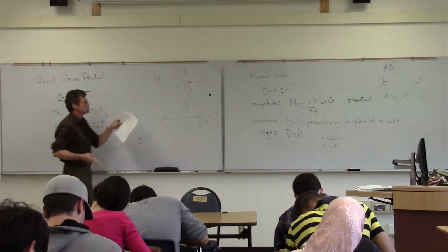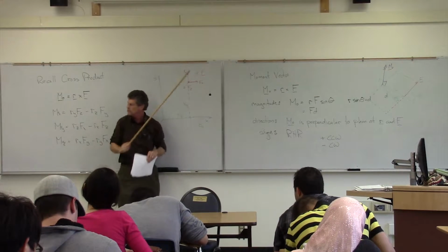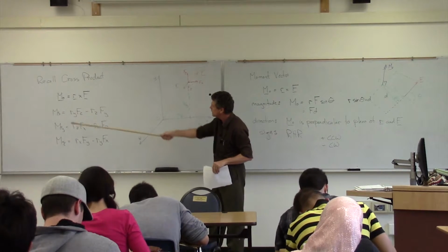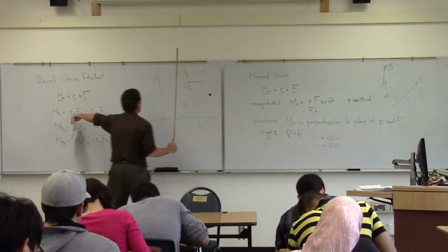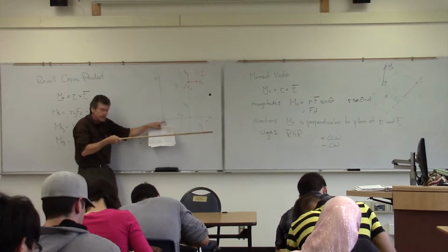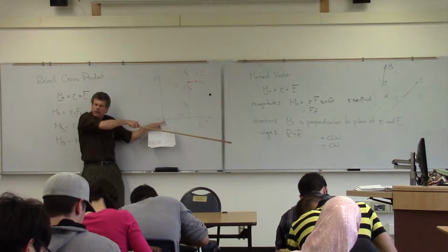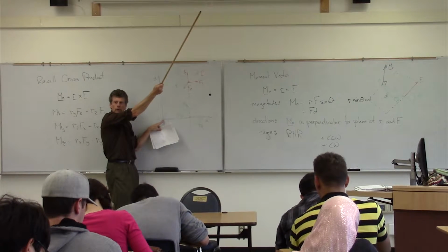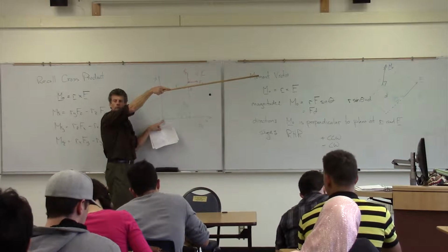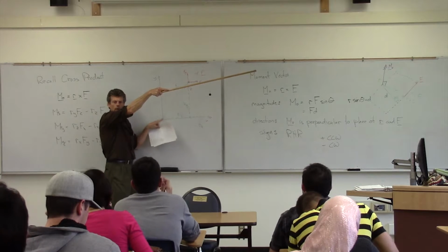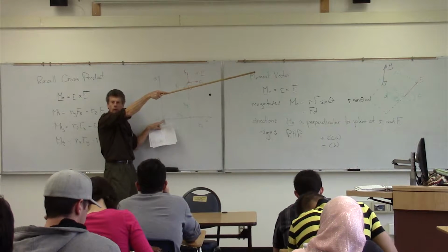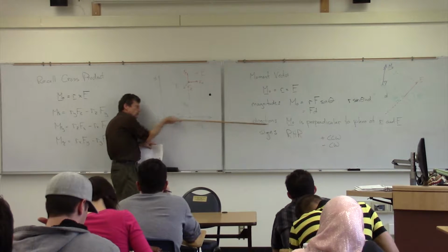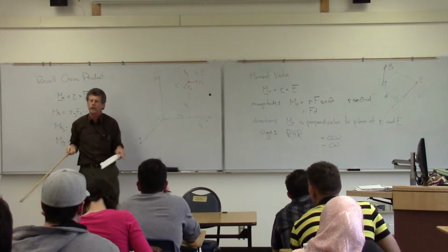So I've got this force out here. And let's think about our x component here. Let's think about this x component. So what we're saying is at point O, I want to know what the twist is about the x-axis. Okay, well, I've got this force out here, pointing off in some direction like that. Let's think about the x component. Is that going to do anything about twisting about O along the x-axis? That force is going that way, so is my x-axis. Parallel, not going to do anything.